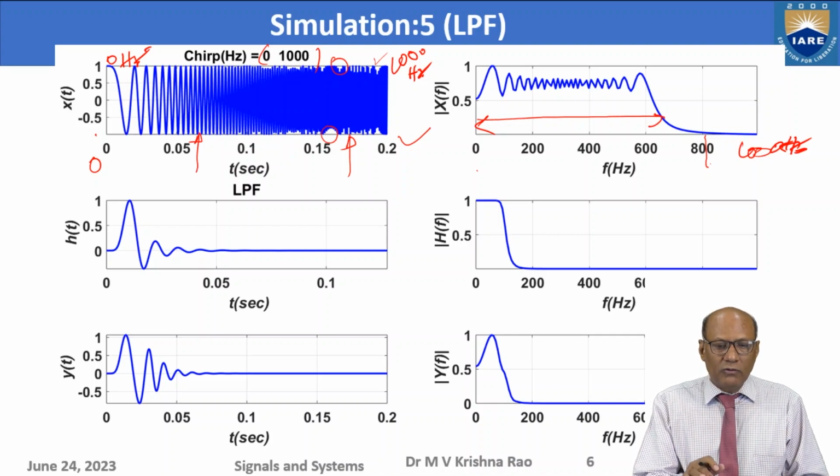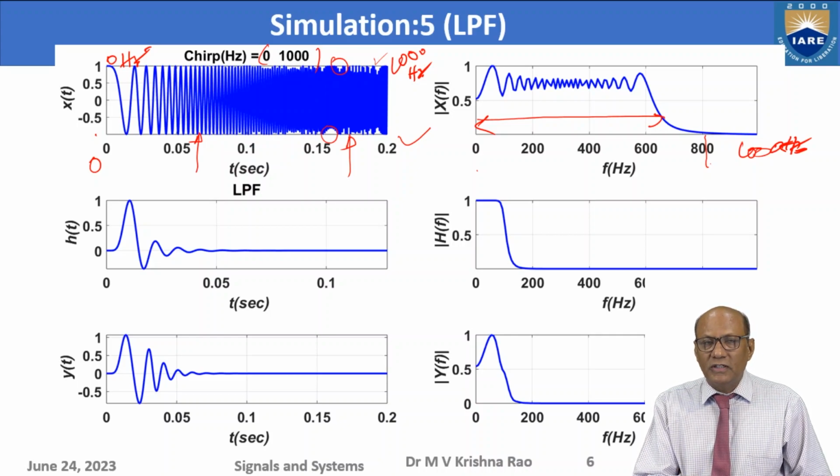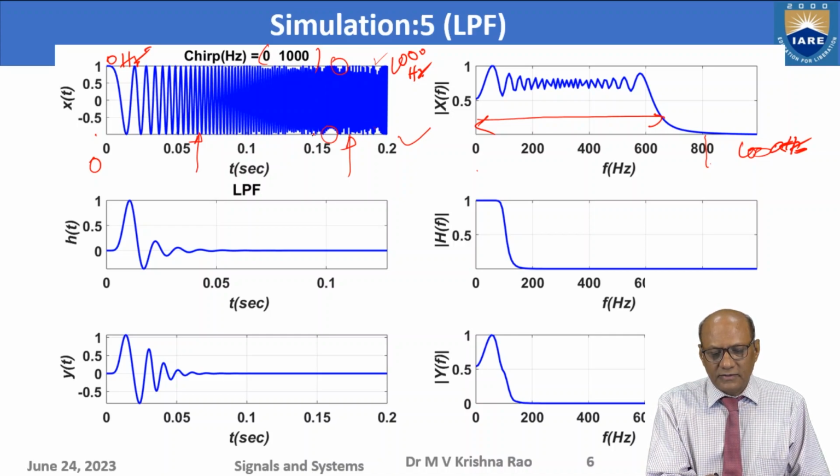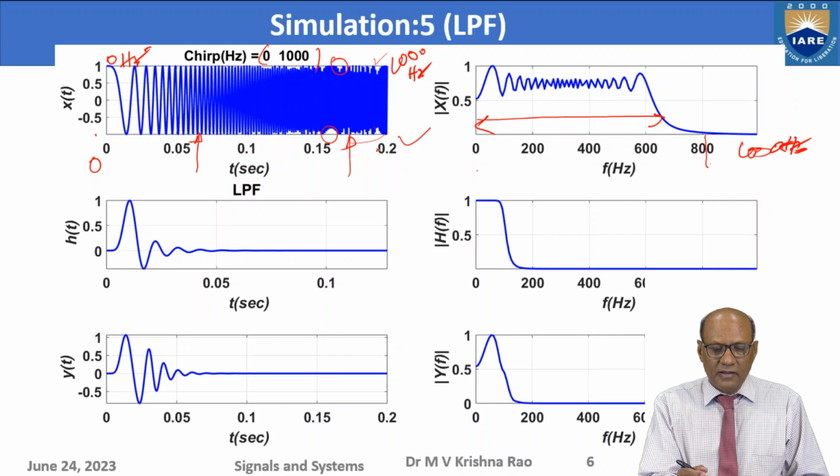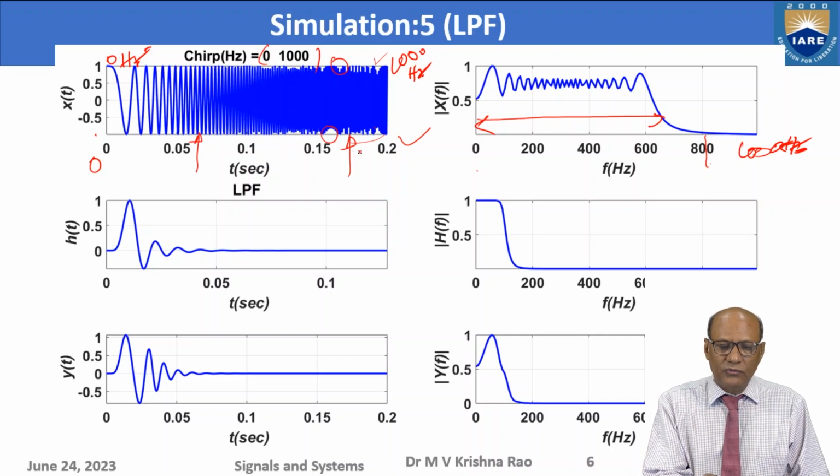So if you go for oversampling, let us say if it is 1000 and I use 20,000 or 15,000, you will get a smooth curve. These wrinkles, these zigzag portions, are because the sampling is lesser but above Nyquist rate only, otherwise we will get wrong signals. So they are above Nyquist rate, but not oversampled. At the lower side you see very smooth curves because those are oversampled.